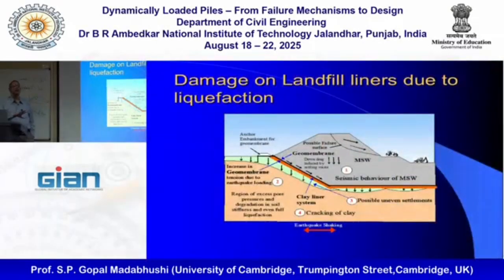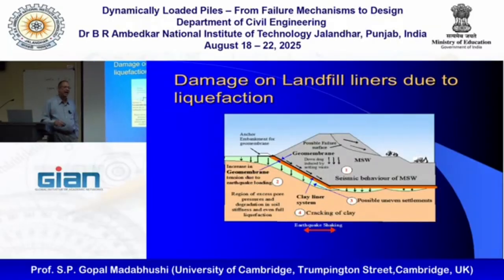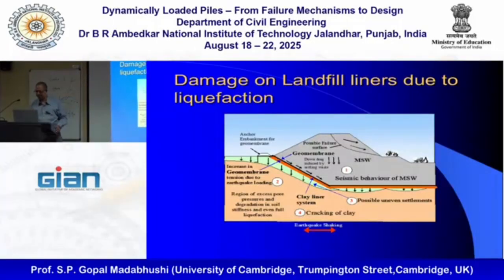This is a new class of problem. Nobody has attempted this, and you can try it, right? We can do centrifuge tests. We create the model and subject it to earthquake shaking, and only the foundation soil can liquefy. The landfill should not liquefy. The clay liner will not liquefy. It's only driven by displacements.